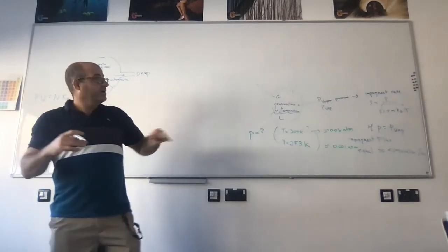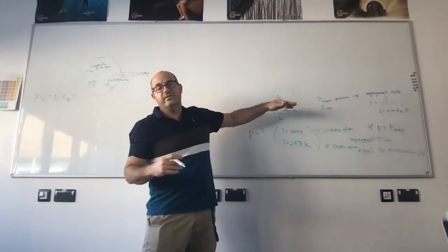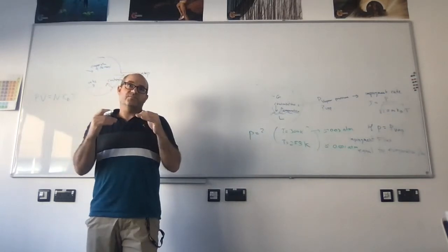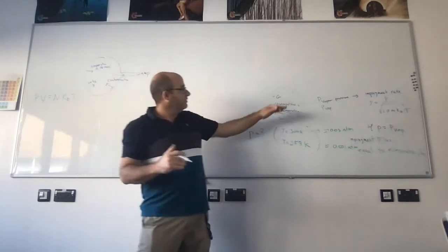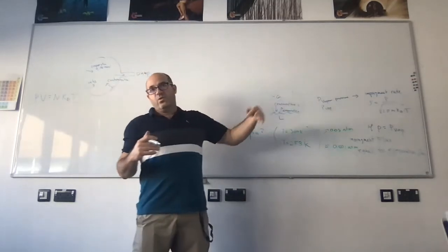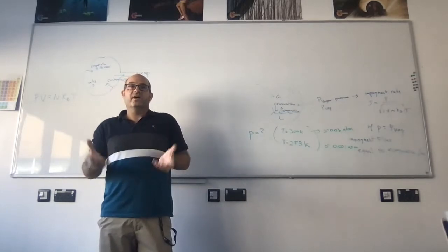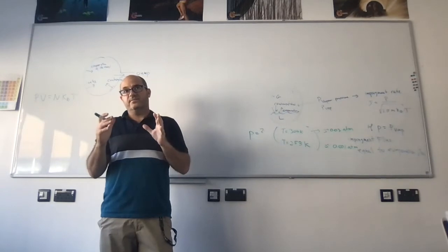You're going to have more and more liquid water until the pressure drops to the vapor pressure. Once it's at the vapor pressure, it's equal again, okay? So if you start by filling it with water at a pressure which is higher than the condensation pressure, you're going to have more liquid. But after a while, it's going to stabilize, and that's it.